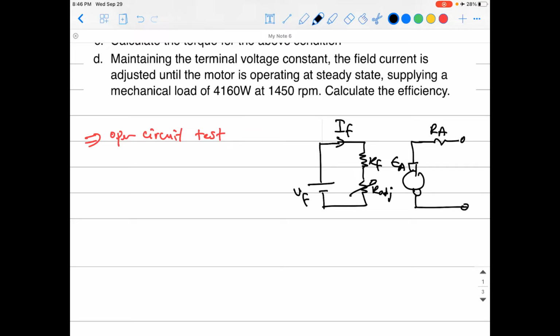And now here's the point. It's open circuit, meaning we're not connecting a load here or anything, or because we're talking about a motor, we're not connecting a supply or anything. That's open circuit here. Okay, rather he's just having a sort of voltmeter to measure the voltage here. Okay, so that is the terminal voltage. Knowing that it's open circuit, there is no current moving here.